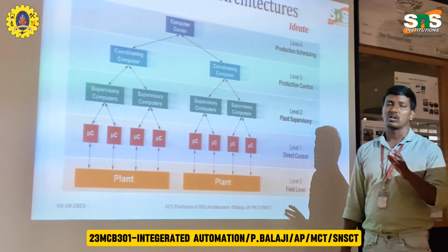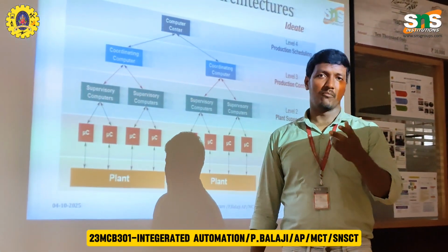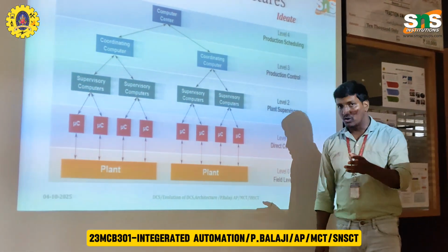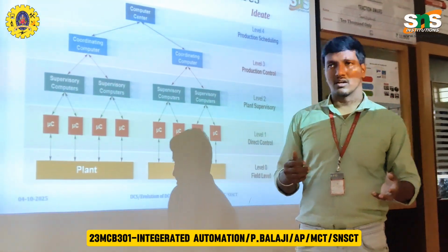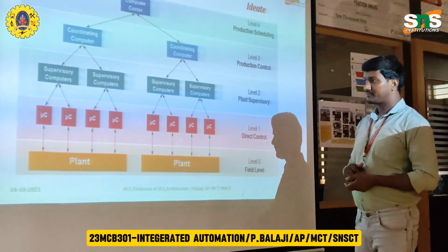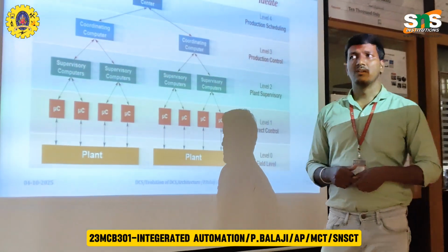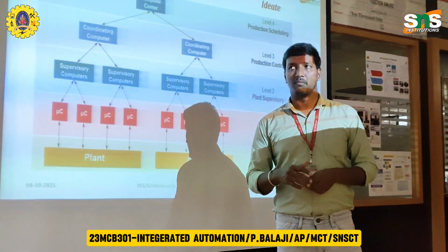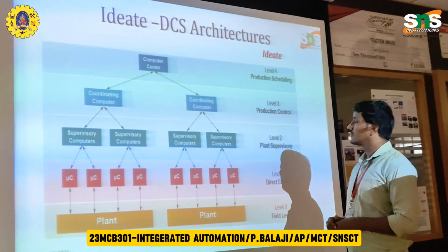If you want to communicate data between high range levels and long distances, we can use PROFIBUS, Modbus, and Fieldbus. Those kinds of buses you can use. But if you want to control the data over a short line, at a low range distance, you can use OSI and Ethernet communications. PROFIBUS, Modbus, and Fieldbus are basically what people use in industry, for power plant applications and oil industry applications. So next.